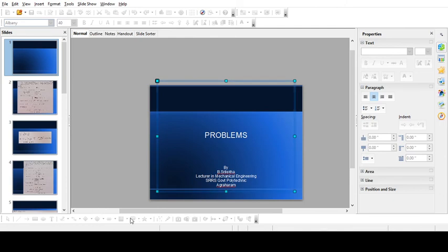Okay, so dv equal to 250 into 100 into 50 into 80 plus 180 minus 220 by 2 into 10 to the power of 5. So in this manner you will find 250 mm cube. This is the change in volume.